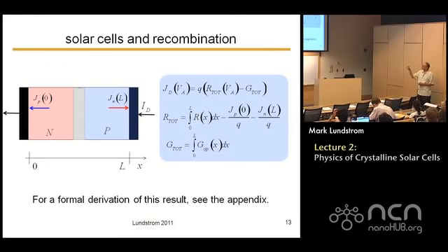So the recombination rate will be the net flow of minority carriers into the N-type contact. If they're not recombining, there will be no flow of current there. And similarly, on the P contact, if there are any minority carrier electrons flowing to that contact, they'll recombine immediately. So that's part of the total recombination in the device. It's the recombination in the volume of the device plus the recombination at the contacts. And the total generation is just the total number of electron-hole pairs that are generated inside that solar cell.